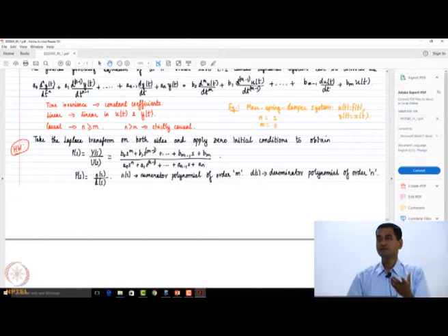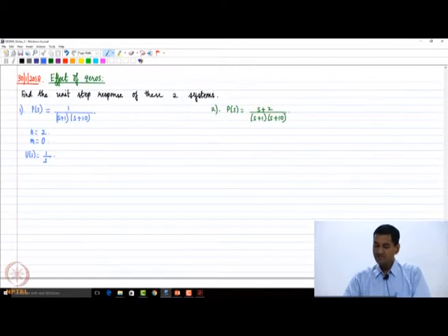That is the general governing ordinary differential equation for the class of systems that we are considering in this course. If you take the Laplace transform and substitute 0 initial conditions, you can immediately observe that the denominator polynomial is going to be an nth order polynomial, and the numerator polynomial is an mth order polynomial. Assuming that none of the factors are common between the numerator and the denominator, we could look at the plant transfer function itself and interpret the order of the system. That's how we write down the values of n and m.